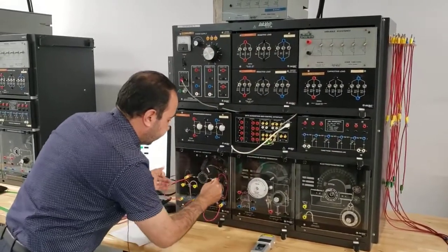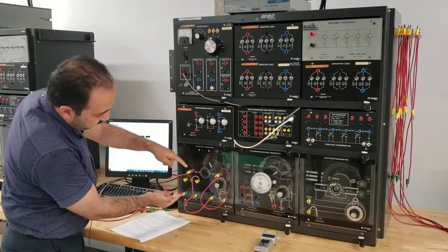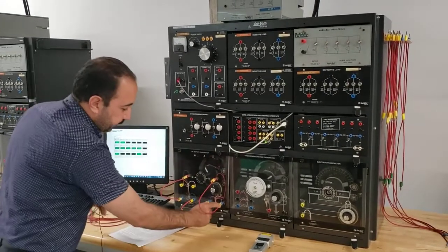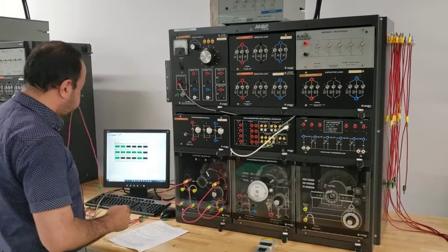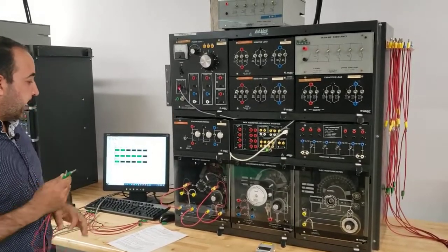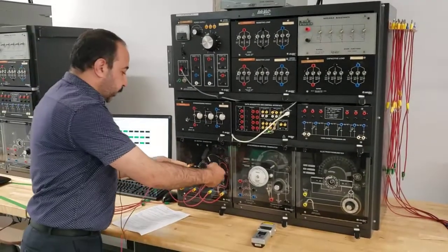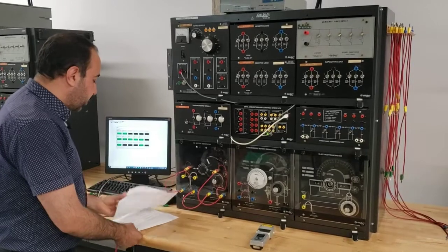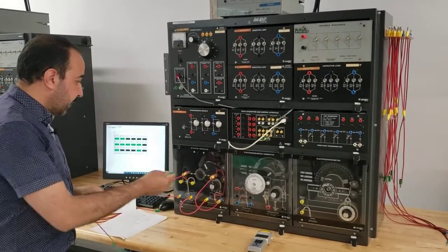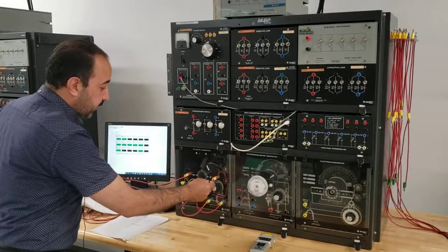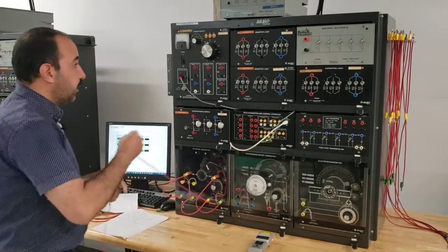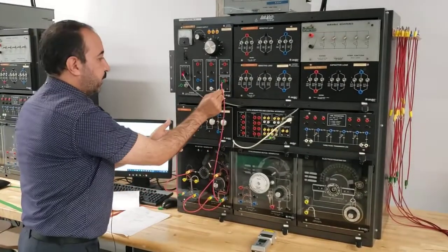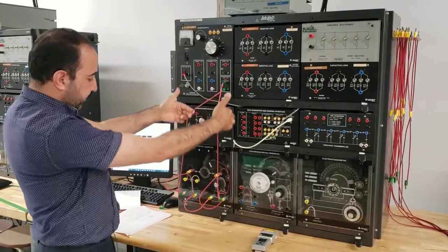At that time, I'm connecting my DC motor in parallel, so I have the armature connected in parallel with the shunt field, and I have this rheostat to adjust the speed. The next step is to feed these two points by a DC source, and the DC source that I'm going to use is a fixed DC source, because I can adjust the value by the rheostat. So I will connect this 8 to this 8, which is fixed, and I will connect this to this. At that time, my field is fed through these two.